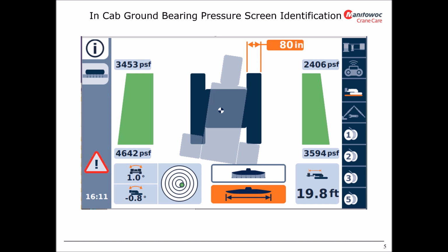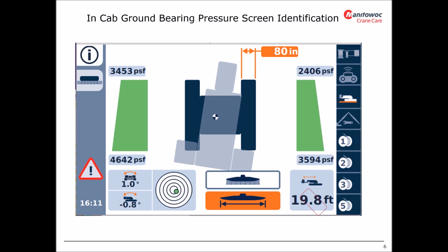The units of measure can be shown in IN, inch, and can also be shown as m, meters, depending upon which unit of measure is selected in the RCL/RCI display, imperial or metric units. The 19.8 ft represents the distance from the center of rotation of the crane to the center of the VPC max trolley in feet. This information can also be shown in m or meters.